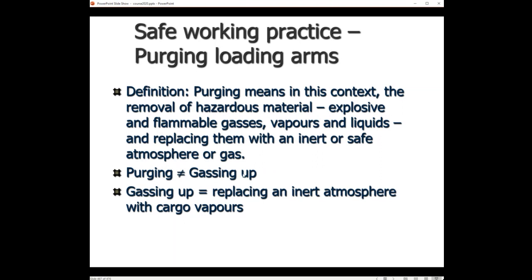Purging and gassing up is not the same. Gassing up is bringing the space, the tank we discussed, under an atmosphere with cargo vapors. Purging is just evacuating the hydrocarbons present in a tank.